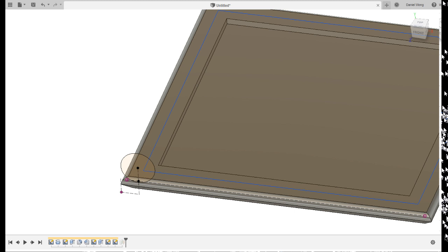When I'm trying to redefine the plane that I'm sketching on, usually that means that you need to actually define a sketch plane, then do the sketch, and not do the sketch, then choose the plane, right? Which is what's happening here, okay? So what I'm going to do, I'm going to make this work, is we're going to roll back one step.